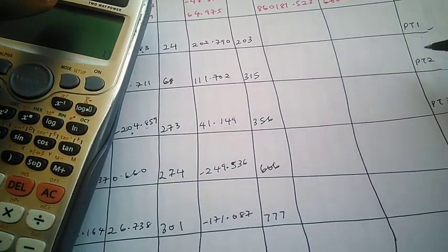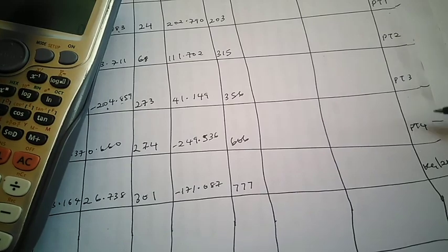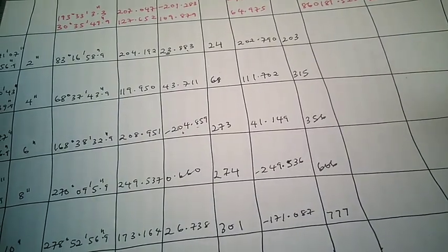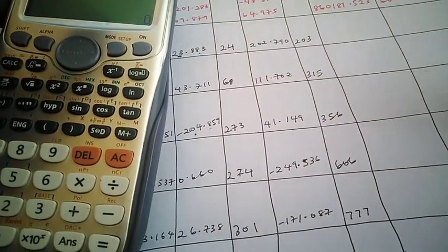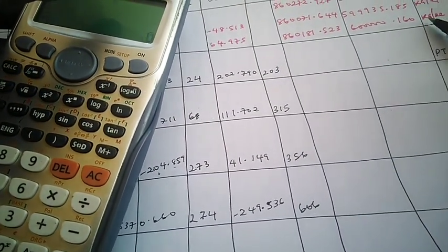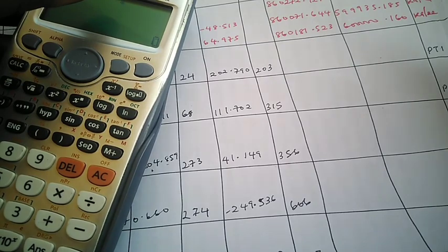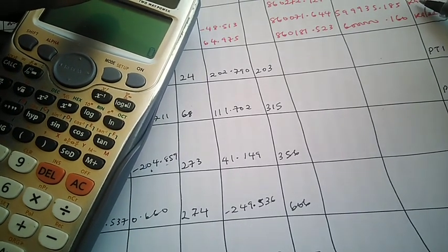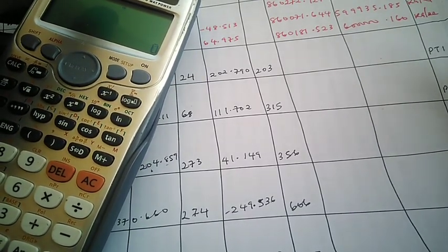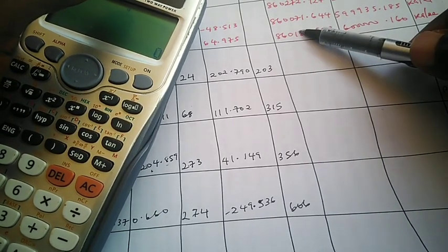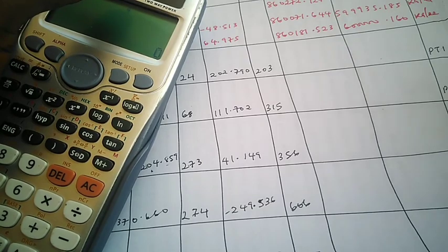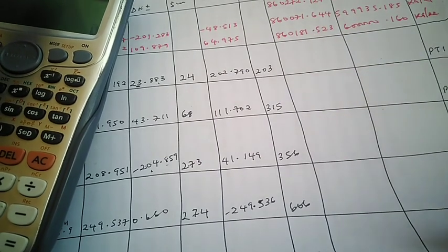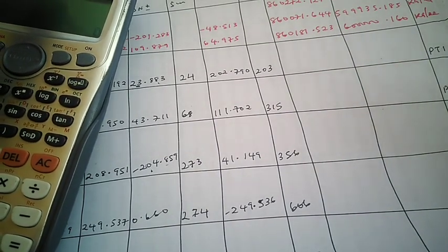When I say new points, I'm talking about points 1 to, let's say, point 4 and subsequently KG21. So now how do we go about it? In one of our previous videos, I was trying to emphasize the reason why I left KG22 here, which is a way to make the work easier for us, because it can actually be in the middle as well. However, I left it here because since the traverse started from KG22, leaving it here lets us easily get the coordinates here, apply them to our partial coordinates, then get the uncorrected coordinate, and we move further.